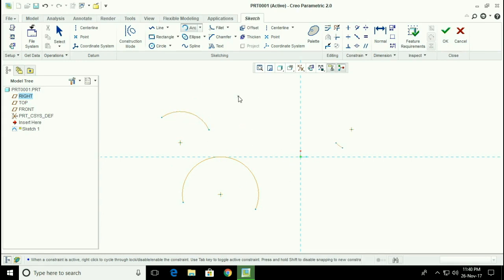For the center and end arc, you will be using a reference circle on which you can draw an arc like this. Center and end. You click and drag for a reference circle, and you click again to draw an arc along that circle. Click, drag, click and drag.